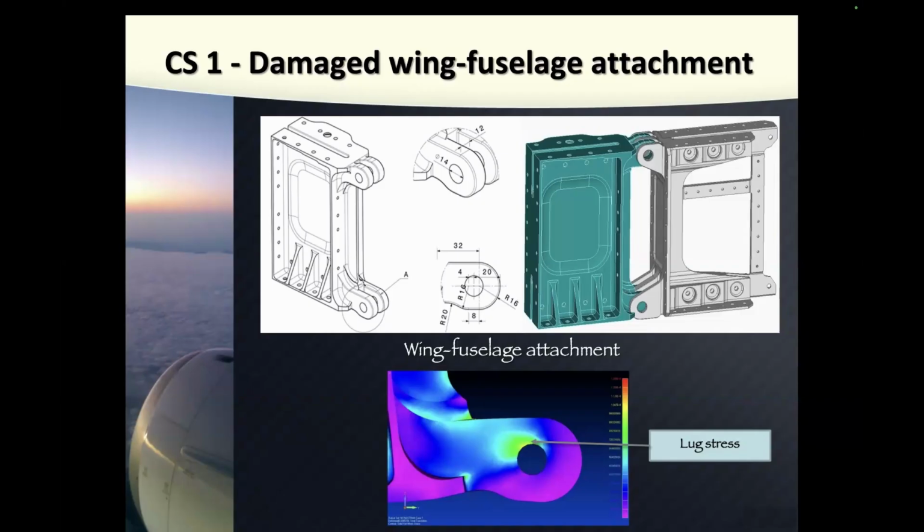So, as you can see, we have lugs, we call them the female part and the male part. Then we just put the pin inside using a hammer, tick, tick, tick, that's all. And this should hold the wing, okay? Now you understand why the fatigue design of this part is critical, because if you lose the wing during the flight, there is no rescue mission that can save your life, okay?